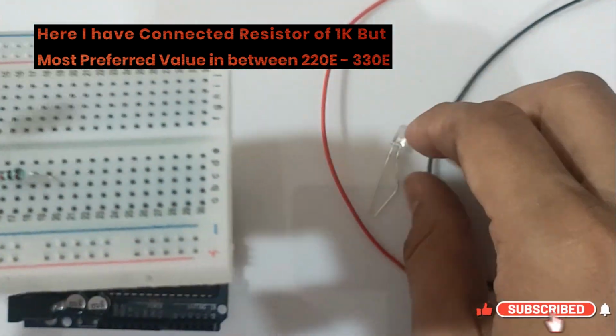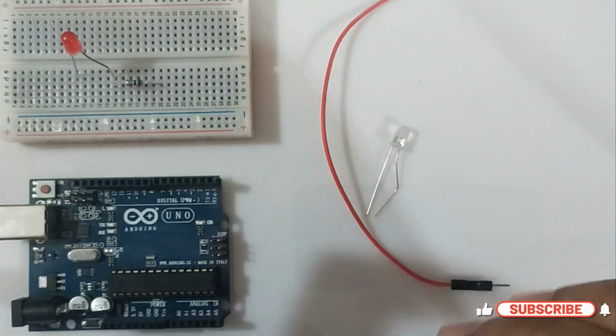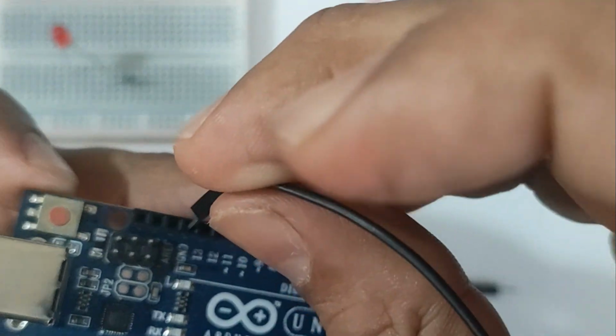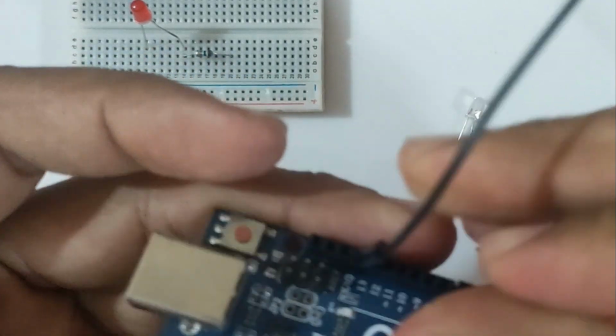Before connecting the jumper wire, first we will make the connections of the jumper wire on the Arduino board. So here we are connecting the black wire to ground and the red wire to pin number 10. So it's done.